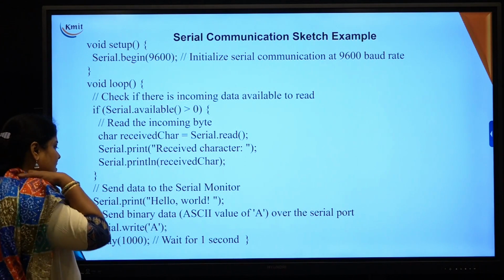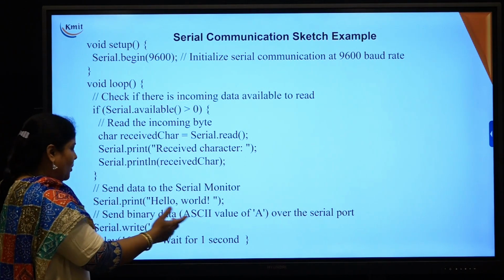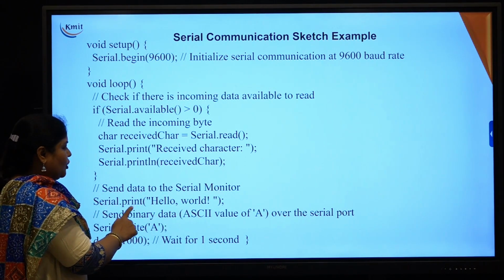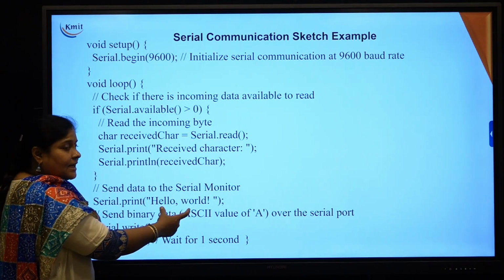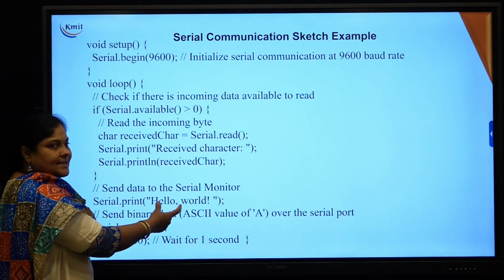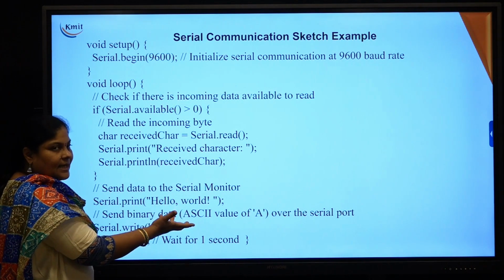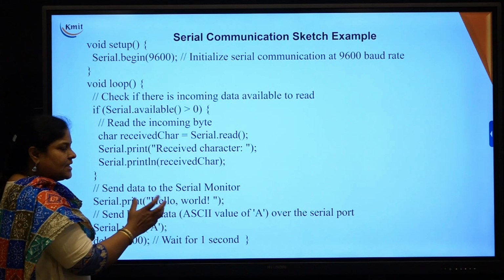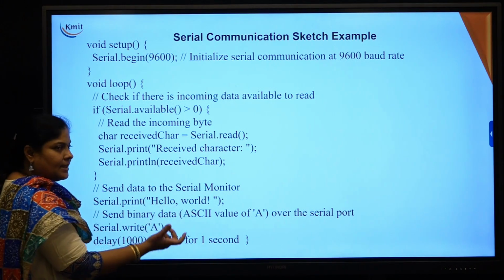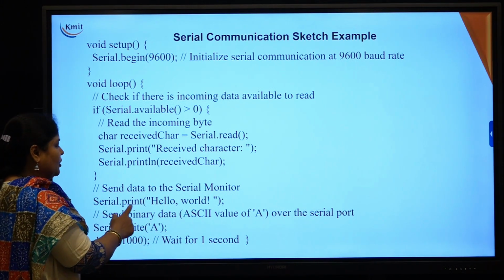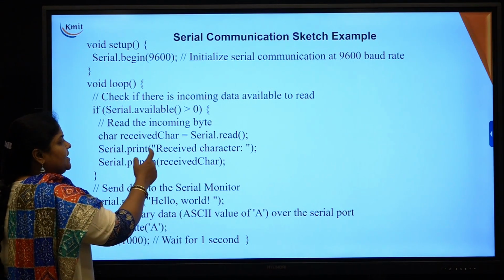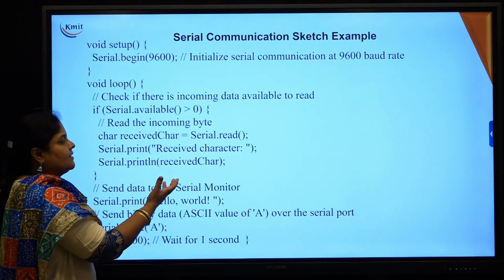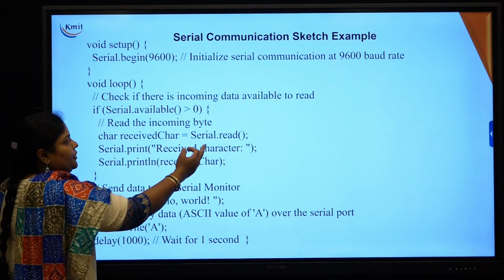And if you want to send some data to the serial monitor, you can say Serial.print hello world. This directly sends the data. Here we are not concerned about any sensor reading or whatever data has been read by the sensor. We just want to print hello world in the output serial monitor. Otherwise, if you want to see the value read by the sensor, you use these methods.